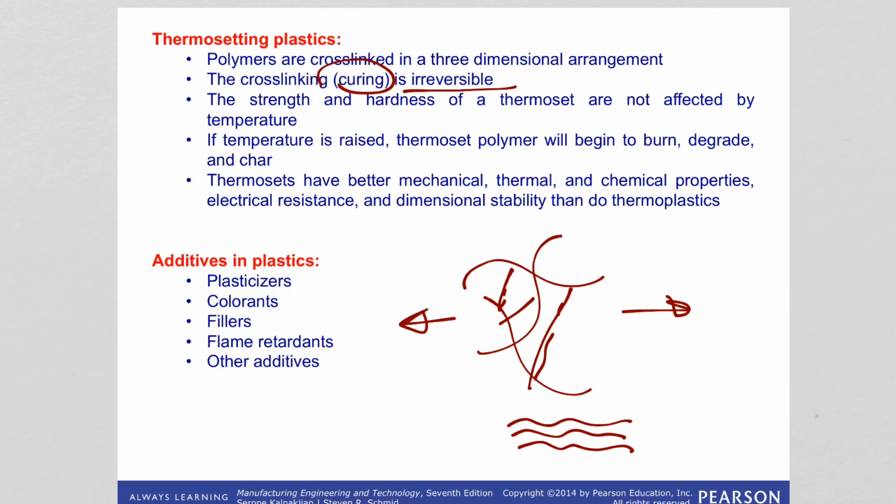So, as I said, most polymers are affected adversely by UV light from sunlight and oxygen. They weaken and the primary bonds break, and there is the splitting of the long chains. So polymers basically degrade, and therefore, to provide protection against the UV, we add carbon black. Okay, so actually the addition of carbon black to rubber is the reason why the tires are black in color.